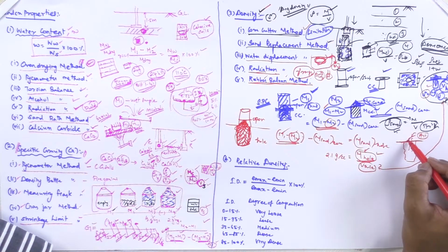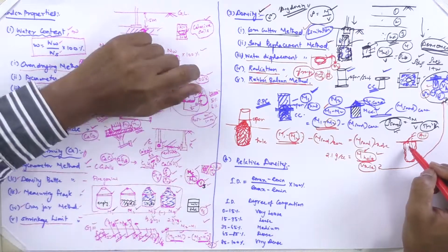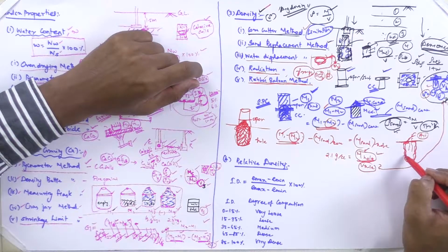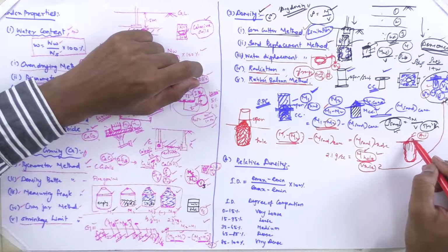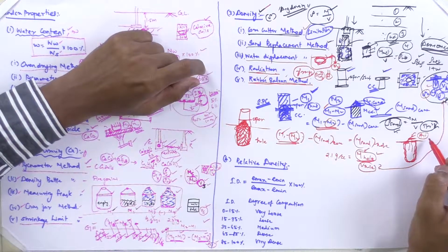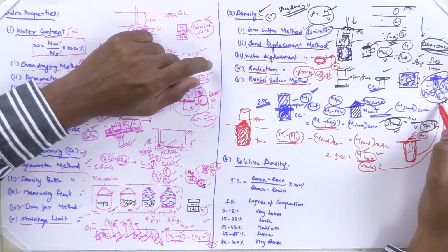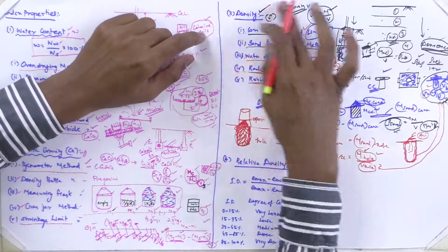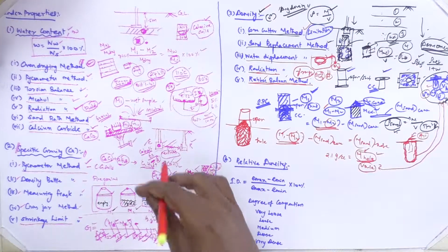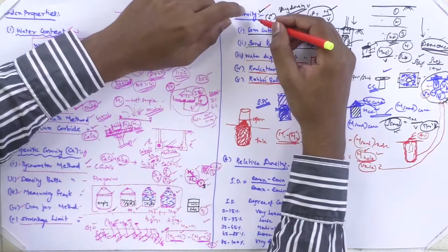While giving air, it is almost filling the whole hole by its surface, by its skin, and once it is filled, you are arresting this, and while taking out, the volume of air present in this balloon represents the volume of this hole, so it can be directly substituted here, very simple. So this is how we are coming through water content, specific gravity and density.